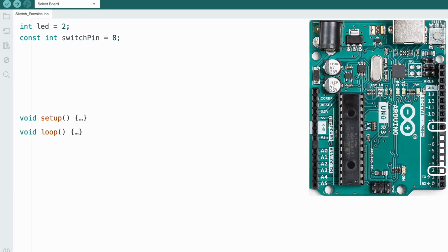Now, the thing about the pins and incrementing this LED variable is we're going to write out to an LED at a specific time. We'll look at a value later on, which is 600,000, which means every 10 minutes. If you leave the variable there, it means every 10 minutes we're going to turn on the next LED. So we're going to leave the previous one on.